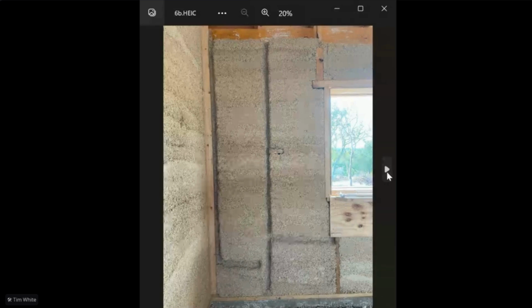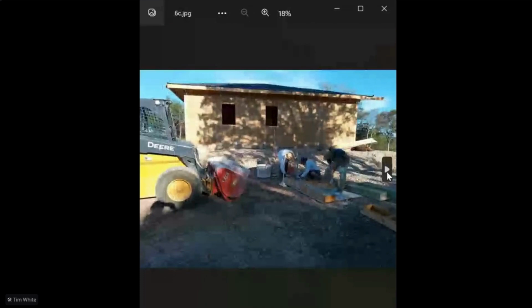And we do those windows with a 2x4 on the middle and a 2x6 on the outside towards the hempcrete wall, basically a 2x4 queen and a 2x6 king. And that 2x6 gives us a spot to attach our formwork to instead of just doing two 2x4s as a post for a window. Works really slick.